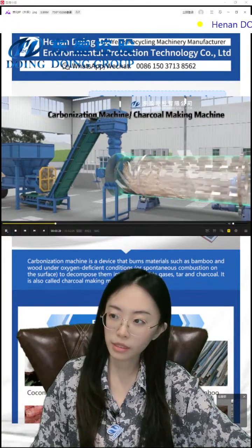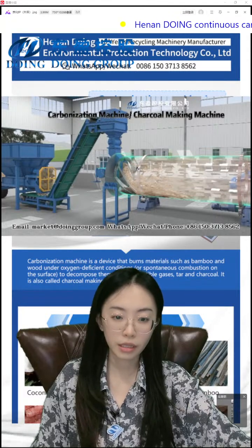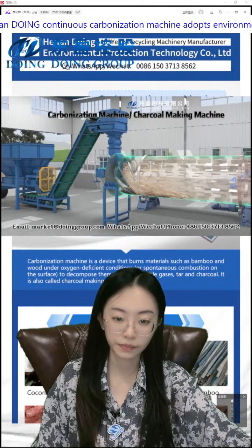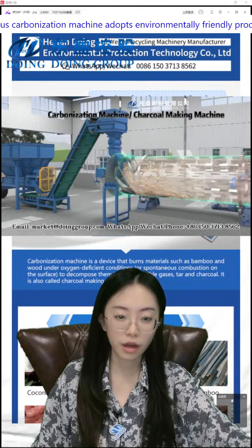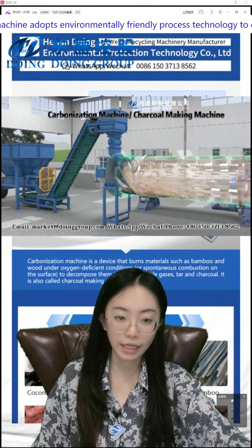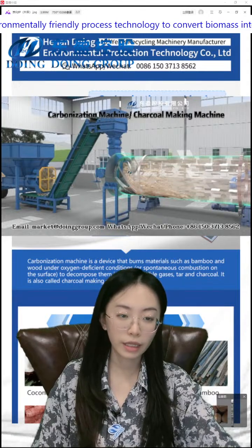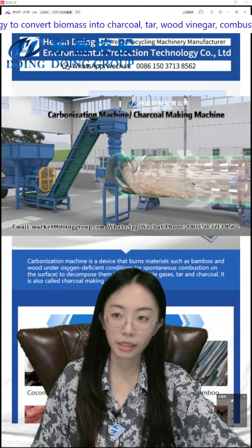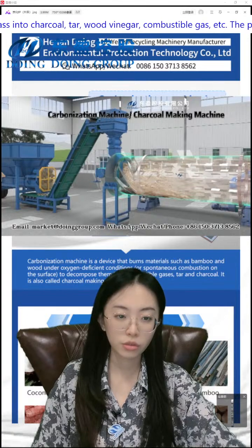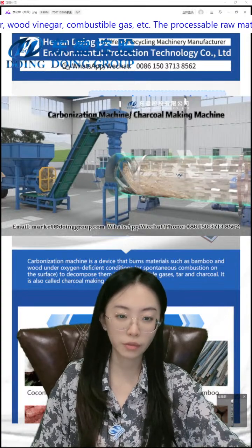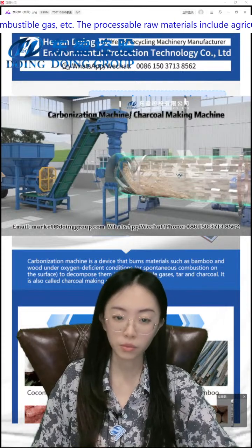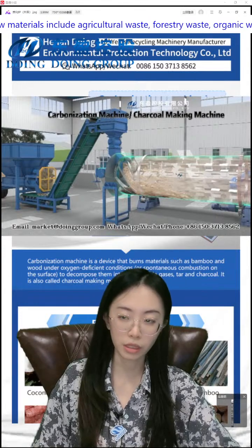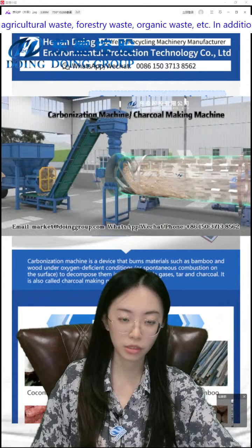And this is the drying machine. It uses airflow to blow the raw material inside. You can see at the front of the dryer are spiral plates to make the raw material go inside the furnace. And inside the dryer, there are many tips, like birds, to turn the raw material so that it contacts the hot air more evenly, and contacts each other, to get the water to evaporate.